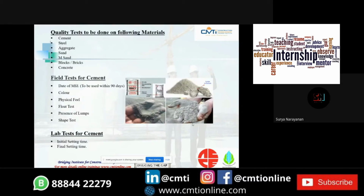These are the tests to be conducted on materials such as cement, steel, aggregate, sand, blocks or bricks, and concrete. First of all, moving with the concept of cement, cement will be checked both in field tests as well as in the lab. The field tests mainly consist of checking the date of manufacture, whether it should be used within 90 days or not, and the color should be greenish gray. The physical feel is that it should give a cool feel when you insert your hand into the bag, and it should give a smooth feel when you take a pinch of cement.